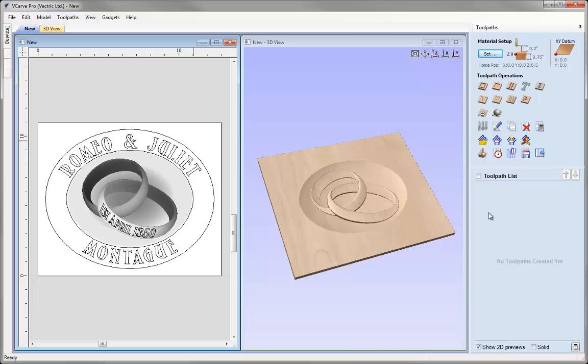Now we'll start by doing our 3D toolpaths, and typically we'd go ahead and create a roughing pass to remove the majority of the stock and allow us to go in with a nice small ball nose tool in order to finish it. When you're working with a dish though, particularly if it's a regular shaped dish like an ellipse or a circle, then we have the luxury of knowing that the toolpath is going to start on the top edge of that dish, and so take a very, very light cut to begin with because there'll be very little depth of cut. After that, you've just got the step over of the tool to cope with, and for a finished toolpath that's typically less than 10% of the tool diameter.